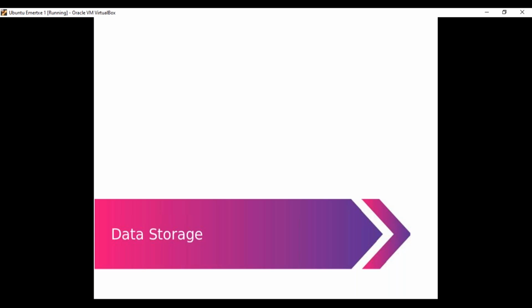If you have code to be written, you can have it written with NOR flash. So depending on the type and the amount of the data, you can choose the memory of your requirement. Now, I'm not going to buy a particular memory, because most microcontrollers come with their own memory.